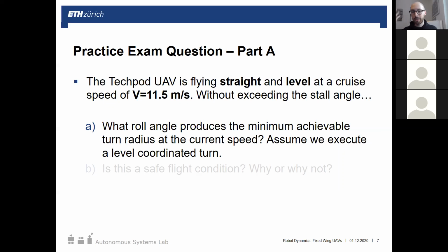if you were taking a commercial flight, on landing you'll see they're actually flaps. They come out and go down. So if our airfoil is originally like this, now we have more surface area and a higher camber. Camber is the curvature on the airfoil. This generates more lift, so the whole idea during landing is to make a lot more lift. They're also making more drag, which is normally okay for landing, since you want to slow down anyway.